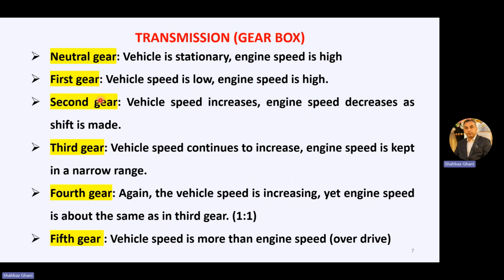In first gear, second gear, third gear, we have gear reduction. In fourth gear, it is a direct drive, 1:1. In fifth gear, it is overdrive. Your vehicle is moving faster than your engine speed.